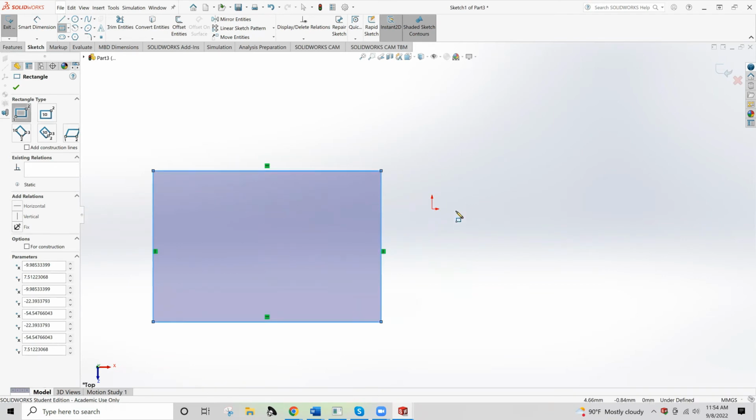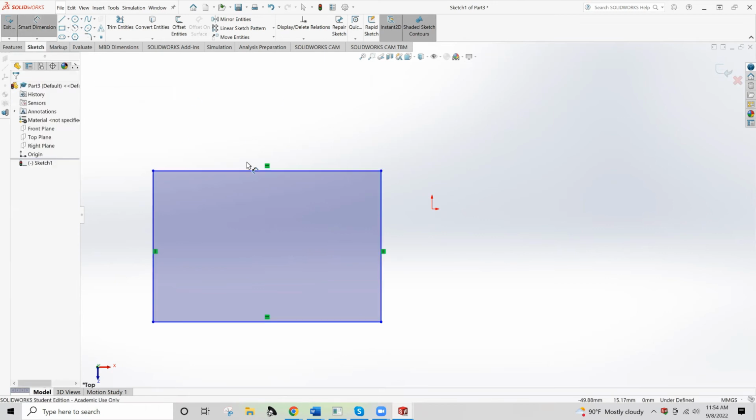There are a few different ways that you can set something like this up. I'm going to use smart dimensions to move this around just to get you in the habit of knowing that if you place something incorrectly, that's not the end of the world. Real quick, I can show you, especially before you add any smart dimensions, the drawing is not, quote, anchored or fixed in the space.